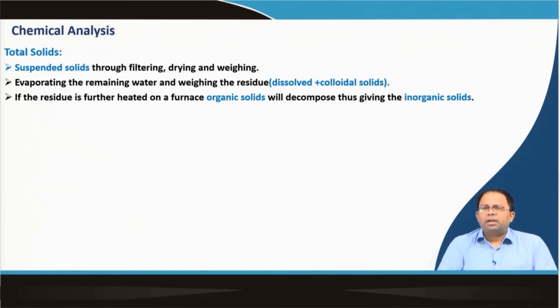We can dry that filter paper, get those suspended solids out of the paper, and weigh them to get the total weight of that particular suspended solids.